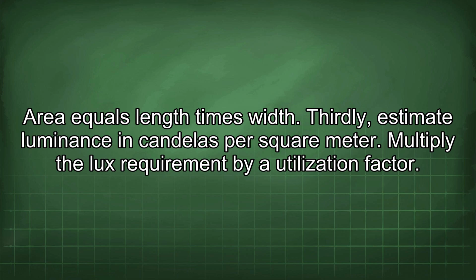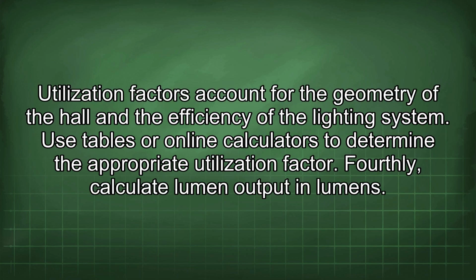Thirdly, estimate luminance in candelas per square meter. Multiply the lux requirement by a utilization factor. Utilization factors account for the geometry of the hall and the efficiency of the lighting system. Use tables or online calculators to determine the appropriate utilization factor.